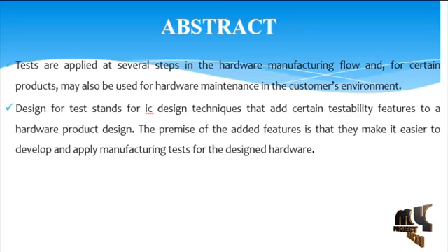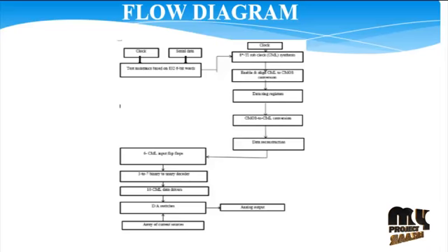Next we see about the flow diagram of our product. This is our flow diagram, and the first one is the clock. Clock enables the flip-flops and other registers, and this is the data. The data is given in digital format, and the DAC works by using the time interleaving of individual sub DACs to provide a composite output that is much faster than the sub DACs.